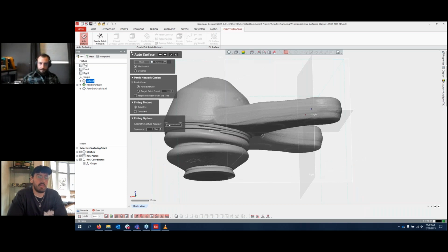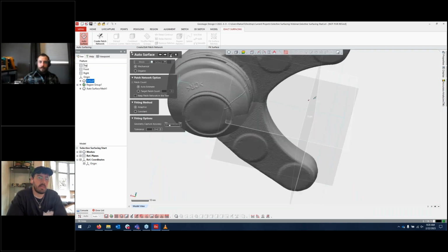And the auto surfacing process looks exactly the same from this point on. So I'll just go ahead and run it. I assume this thing is surfaceable. I think when it creates that new mesh, it actually runs the healing wizard as well, because that's a pretty critical step before auto surfacing. And since we know that's where this file is going to go, we run the healing wizard as well. So wait about a minute or two for this to complete running.